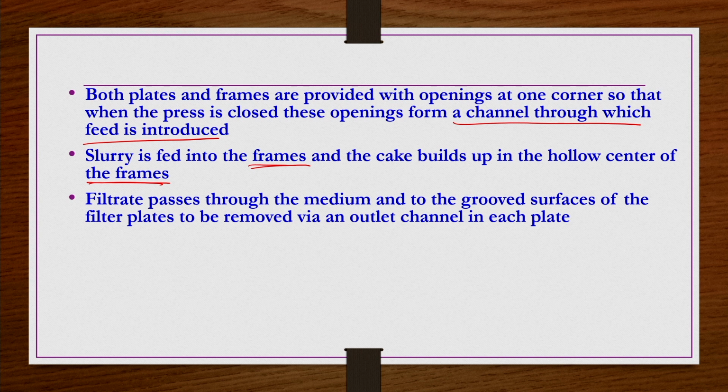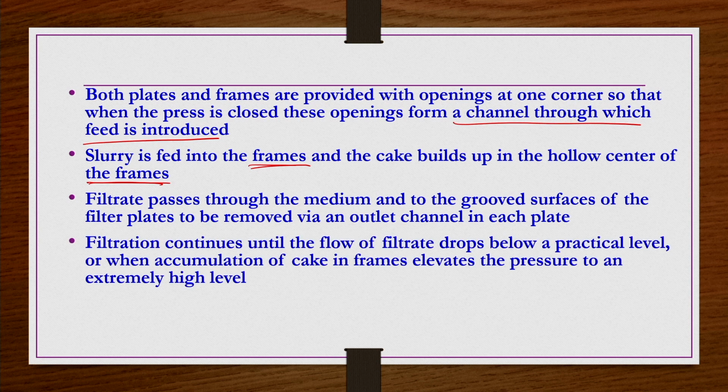Inside the hollow frame, cakes are being deposited, right, because the filter medium or filter cloth covering either side of the plate allows only liquid to pass, and the solids are collected in the hollow center itself. Okay. Filtrate passes through the medium to the grooved surface of the filter plates to be removed via an outlet channel in each plate, and filtration continues until the flow of filtrate drops below a practical level, or when accumulation of cake in the frames elevates the pressure to an extremely high level.